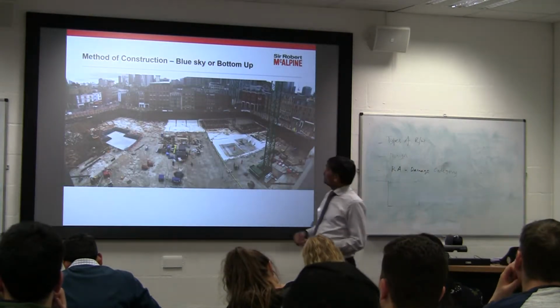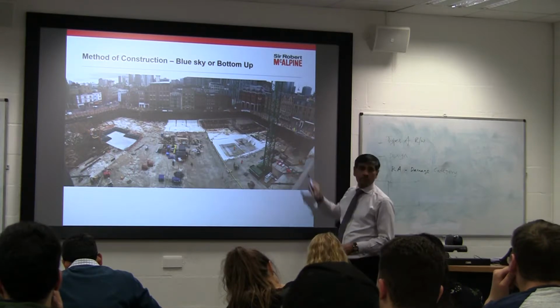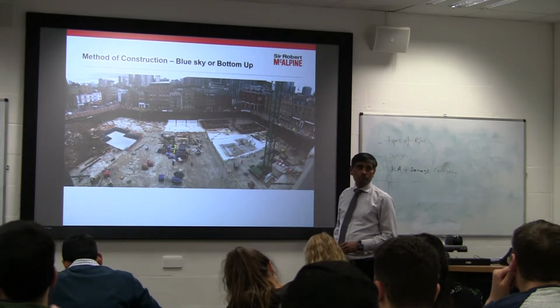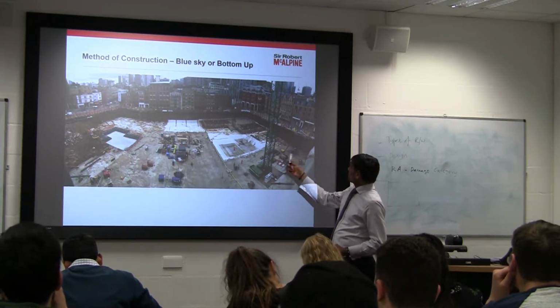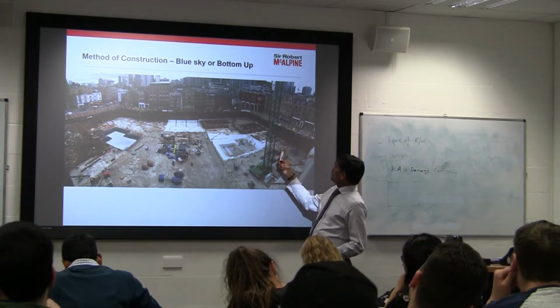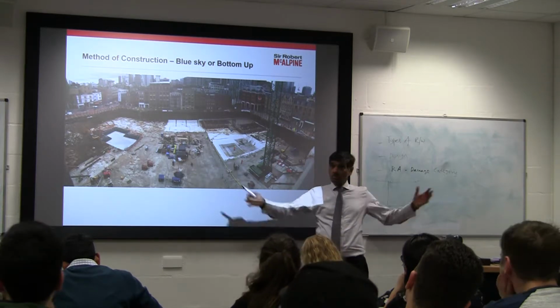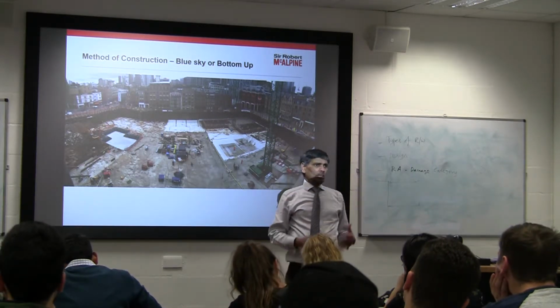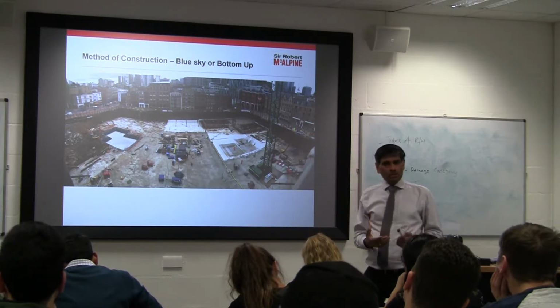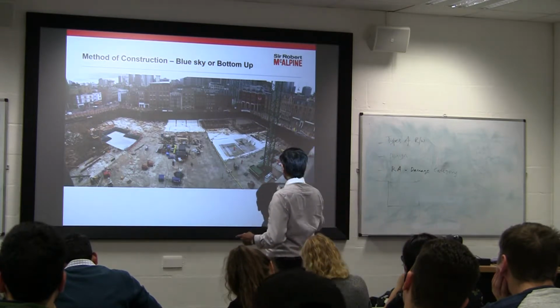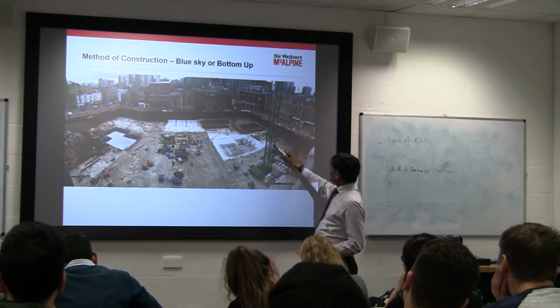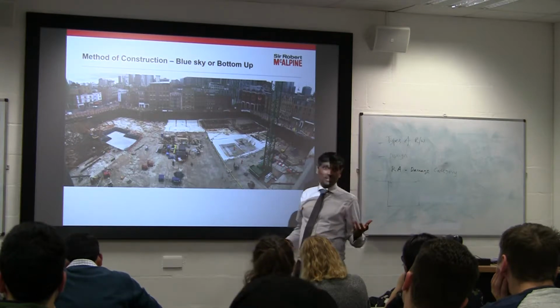So if you can see here, that's what we have done, raking prop. Yeah? So the beauty is that you can see the size of these machines can get in. If you want to do any piling or any other work, the gap between them is about 8 meters. It's more than the dimension that way. So that's the same dimension. You can keep them at very close spacing, it'll be very tight. You can see if you keep them very close, then the size of this prop will be reduced or increased.